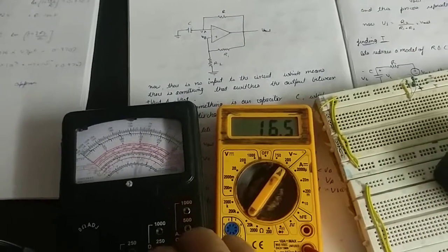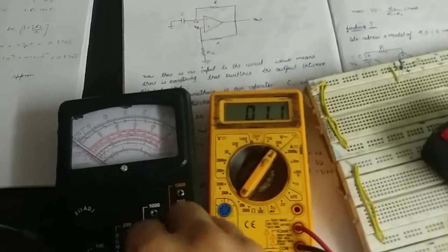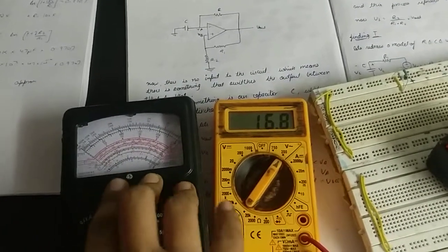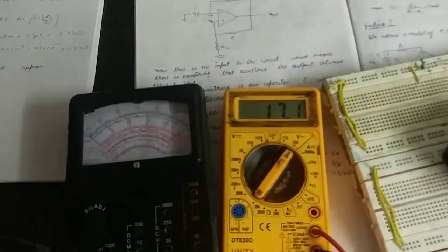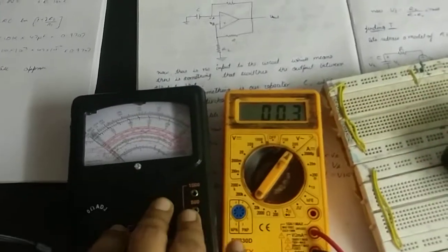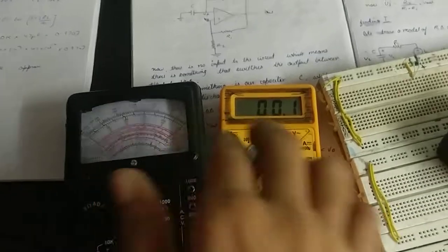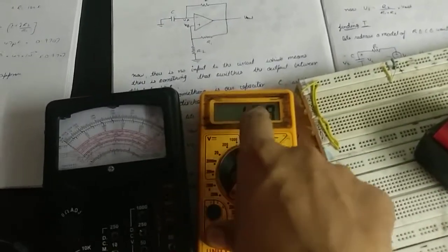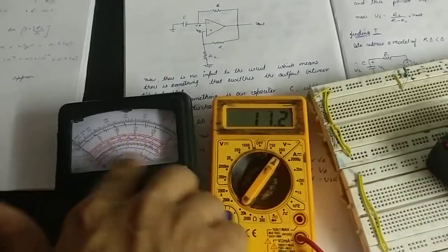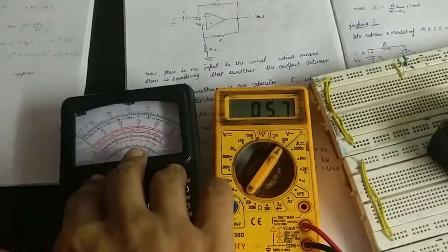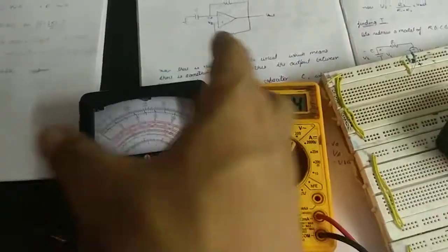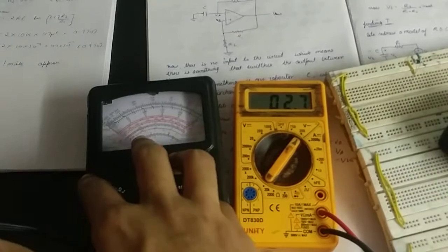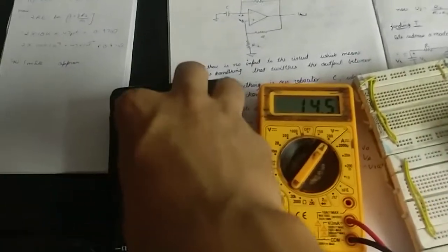So this was all about the analog multimeter, and this simple trick of how you can use an analog meter to see oscillations. It's a really fun thing to do. You can change all sorts of waveforms, and if the frequency is really low, you can visualize it. With this digital multimeter you won't be able to do it. It can show you the numbers between 0 to 18, but it can't show you this particular movement. This is very useful if you want to analyze things, and that's why I consider using an analog multimeter along with a digital one when you're working with oscillators and analog circuitry, because it comes in really handy.